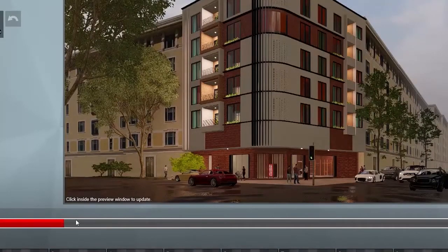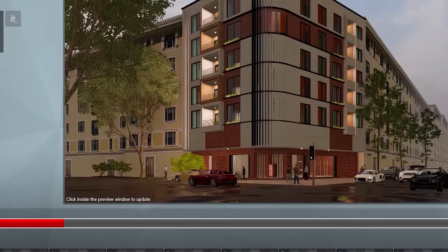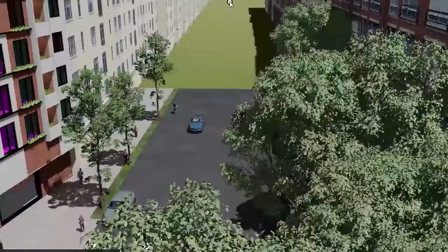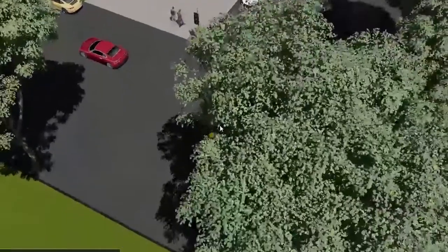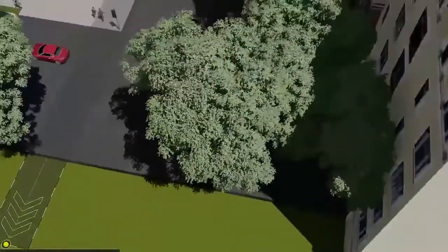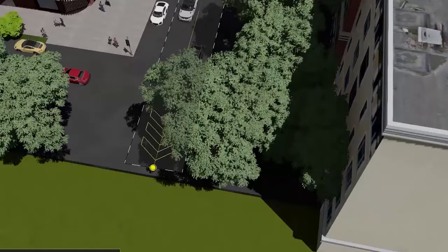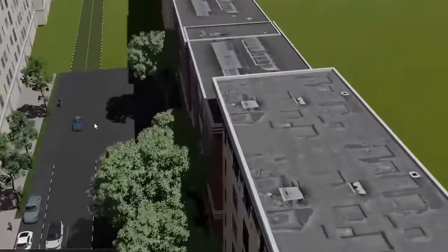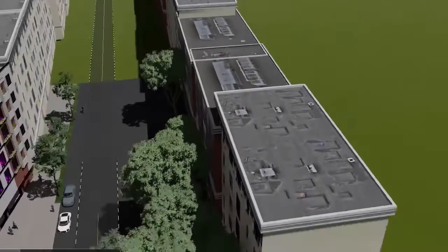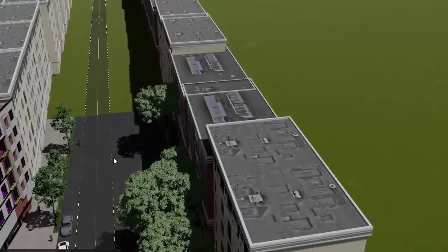And one thing that we want here is to let some people walk and some cars to be driving. We go to animation and we click on mass move. We choose edit and pay attention. It's true that we don't have our asphalt here, but we continue the way till here. Increase the width. Refresh it and we move it again. As you can see, you can increase or decrease the movement and speed of the car. And they are moving at 60 kilometers per hour.